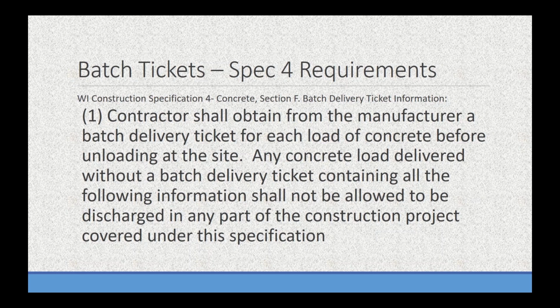You're going to need it before the concrete load is unloaded so that we can check it and ensure it meets Spec 4, because after the concrete is placed, that's too late if we find that issues arise and it doesn't meet the Spec 4 requirements. It goes on to say any concrete load delivered without a batch delivery ticket containing all the required information shall not be allowed to discharge in any part of the project. So it's pretty specific. We need a batch ticket delivered with each load. We need to get it before the truck is unloaded at the site. If we don't have that, they should not be unloading or discharging that concrete at our project.